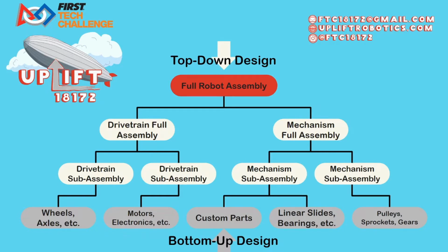Instead, top-down design starts with creating the full robot or mechanism assembly in your design first, and working your way down through your model to the sub-assemblies and then the individual components. By using this approach, changes made to one of the assemblies will automatically be trickled down to the parts. In order to propagate the changes from assemblies to the individual components, we use skeletons, which essentially hold all the information for that assembly and send some features of it to each of the components.